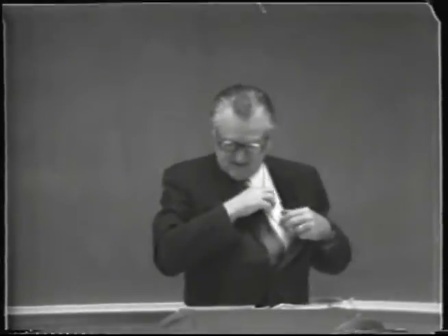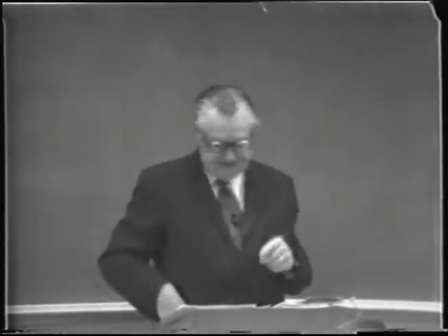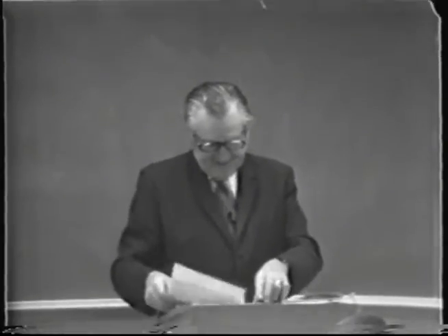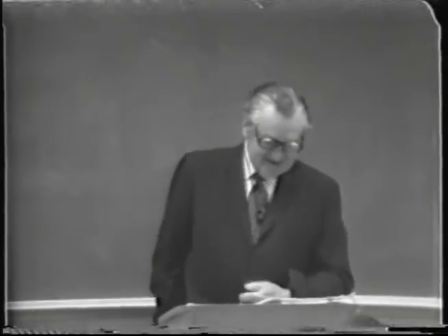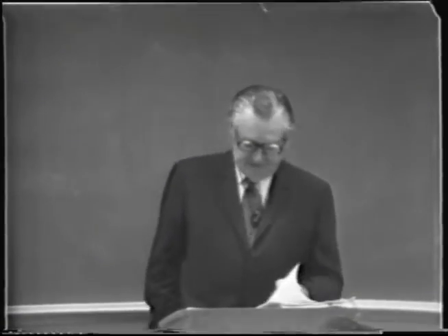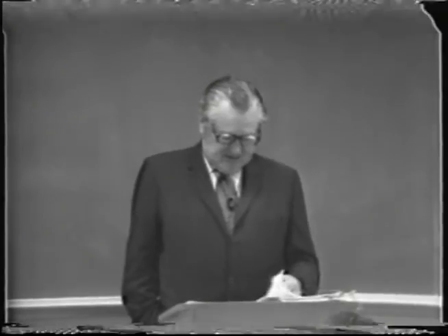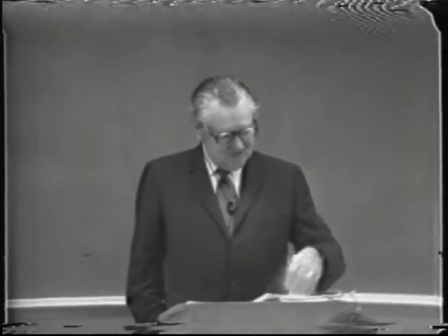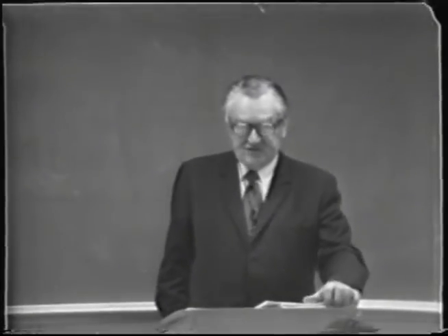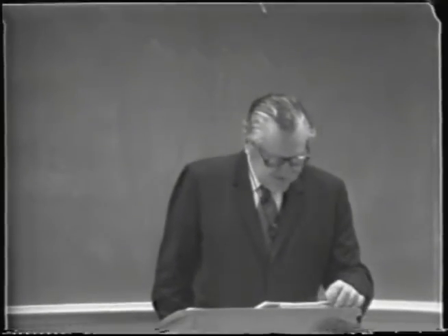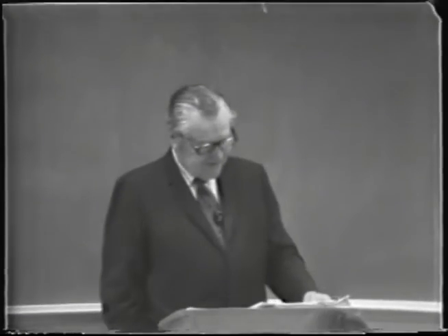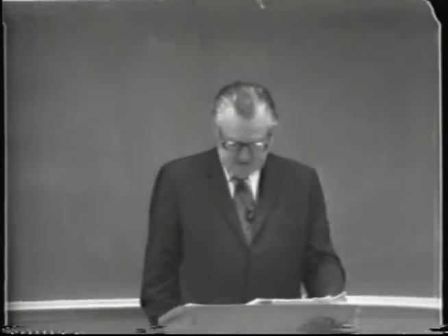There's a few final points I'd like to take up today having to do with distillation processes, and first I was going to say a few words that some of you are particularly interested in and didn't quite understand at the end of the last period, having to do with steam distillation economizers, or the so-called use of the principle of recompression for obtaining some additional steam requirements by flashing off some of the vapor from the stillage.